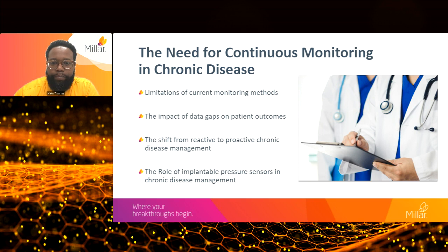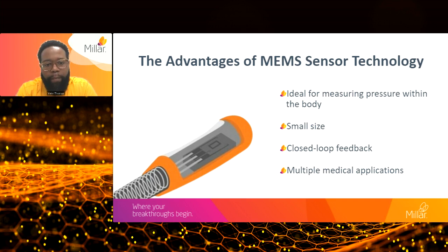In terms of selecting the right sensors for device developers, there are many options, but choosing the right sensor matters when it comes to reliability and data that you can trust. For this conversation, we'll be focusing on the advantages of MEMS-based sensors, MEMS meaning micro electromechanical systems. These sensors take a mechanical input and translate that to an electrical signal that can be quantified and measured and provide needed insights. MEMS sensors have been used in medical device applications for decades and are well understood. So this minimizes the risk associated with deploying novel technologies.